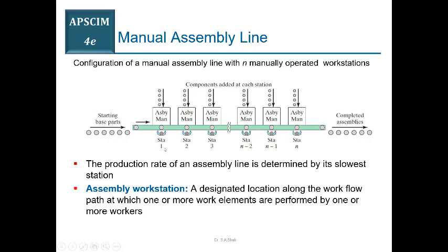That slowest workstation decides the cycle time of the system, and cycle time is the time in which you get one finished part out of the system.